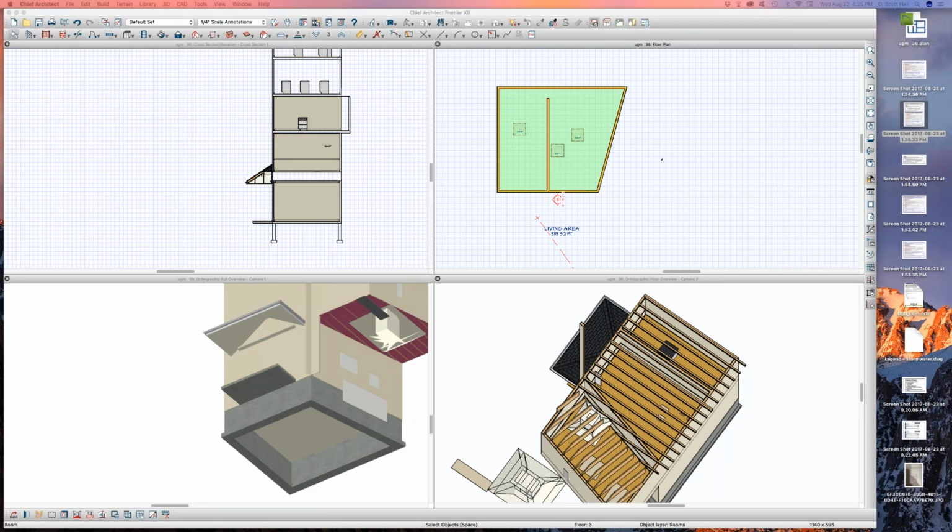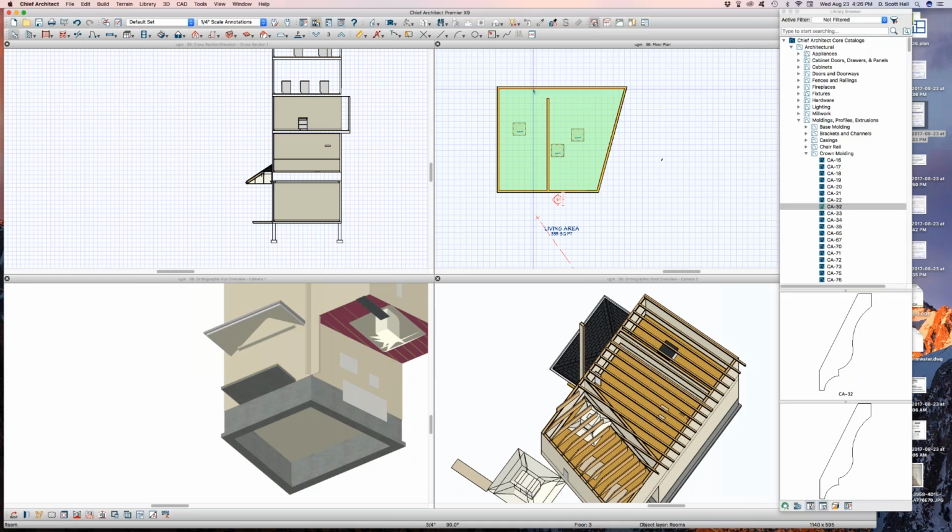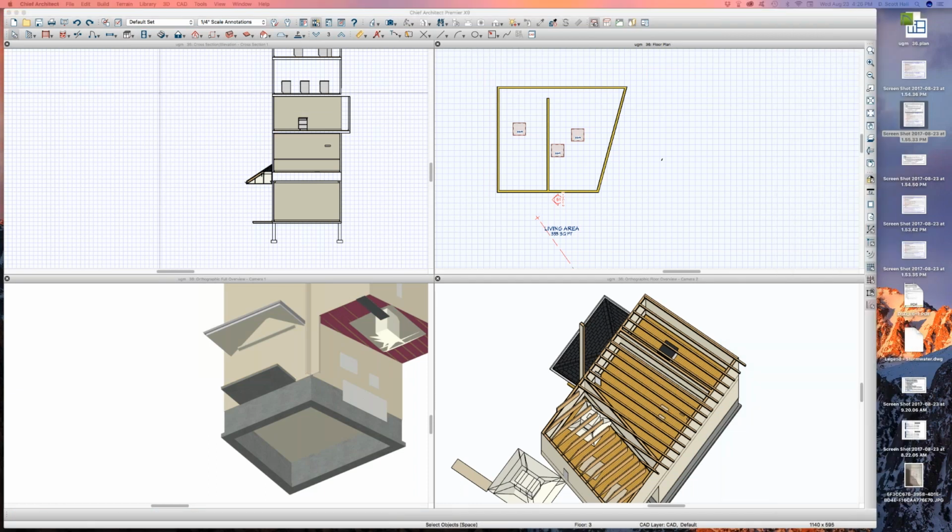Why couldn't you use just a molding polyline for that? That's what I did. But I think the beauty of what we said, I was trying to automate it. Yes, so if he changed his basement size, that drain tile would go with it. Oh, okay. And with a molding polyline, it doesn't. Yeah. I was hoping next time I did a foundation, it would draw it in just by naming it the slab, or whatever I named that room. I don't remember what I named it.